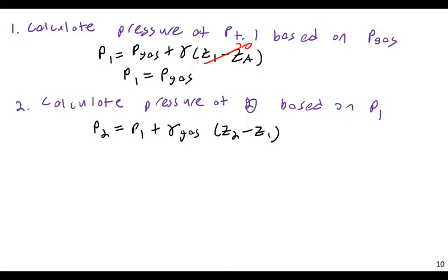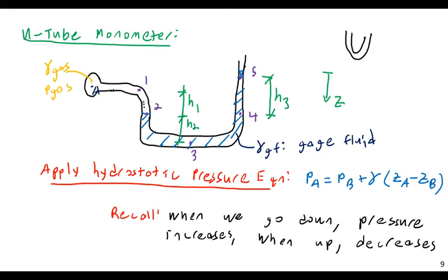And since this gas is higher than atmospheric pressure, that relative height would be even greater. So that little difference in height for a gas is going to be negligible. The difference in pressure between here and here, because the density of a gas is so small, we can really neglect it.